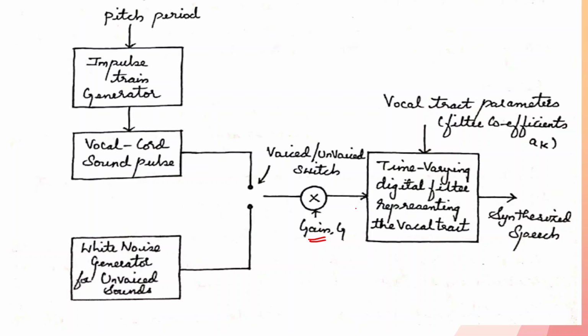And finally, they are encoded in a sequence of binary digits and transmitted to the receiver. The voiced or unvoiced information bit activates the voiced or unvoiced switch, which selects either the impulse generator or the noise generator, feeding the prediction filter.